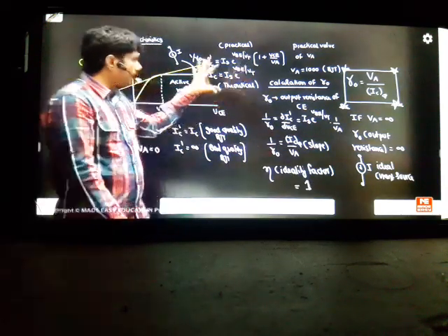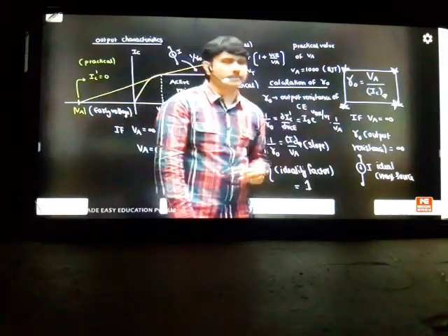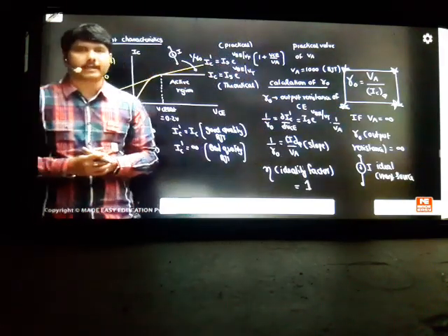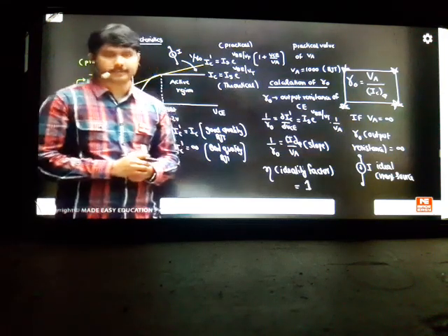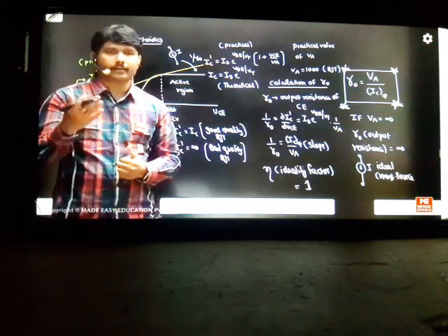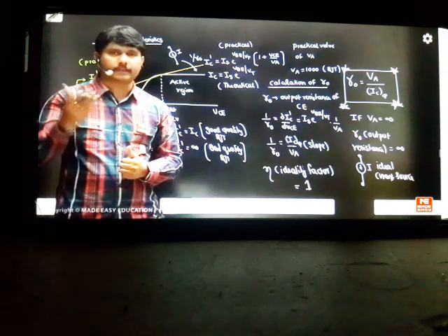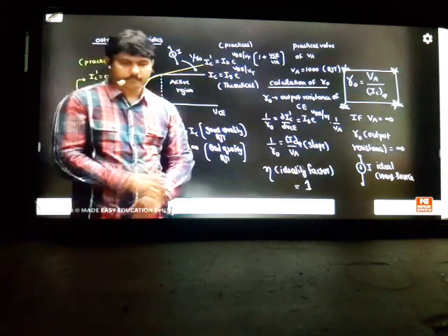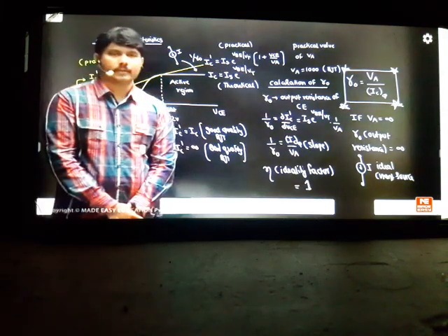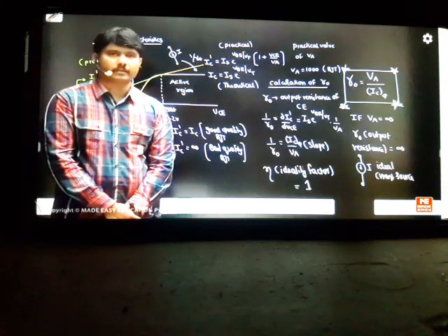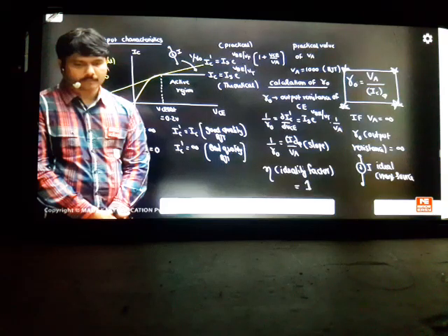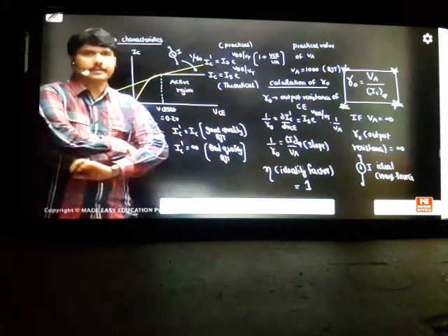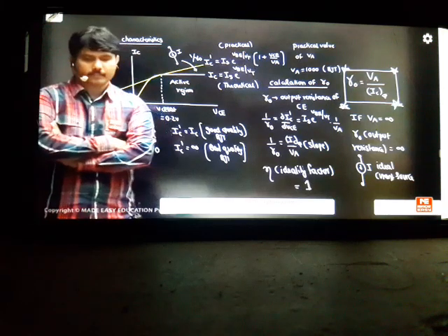From the exam point of view, this total information is not important. This information is important, and this formula we should not forget: output resistance is always calculated as early voltage divided by the operating current of your transistor. This formula is used recursively in the coming amplifier classes. If you don't know the early voltage, we cannot define the output resistance of a common emitter transistor. If you know the early voltage, we can define it. With this, we have covered the main concept, the story of VA. We will now convert that knowledge to lambda in the class. It will become easy for you. Please tell me if it is completed, and we'll move to the next point.